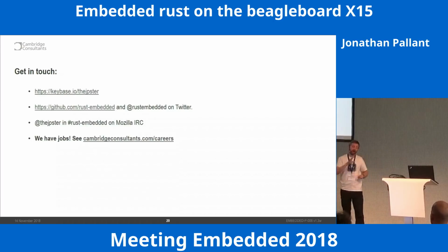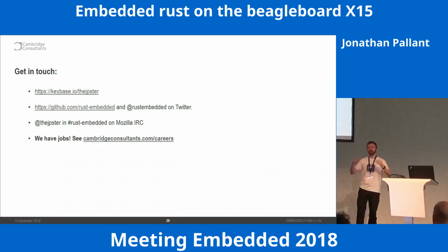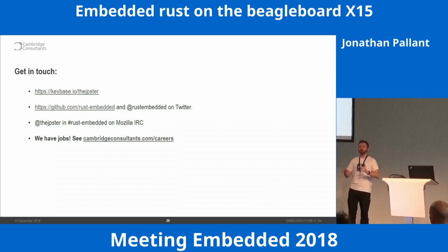Yeah, it's a good question. I showed you the unsafe bits because they're the interesting bits. It's basically booting the chip and accessing hardware. I've got to do it through raw pointers, but you almost always hide that behind a safe API. You work out what a reasonable interface is, and that interface is written in normal, safe Rust, and then inside we go, okay, here's an unsafe block. I know this is the address of my shared buffer. I'm going to dereference that address. I'm going to add a little comment here that says, I've checked this address. You can find the value of this address in this data sheet on this page.